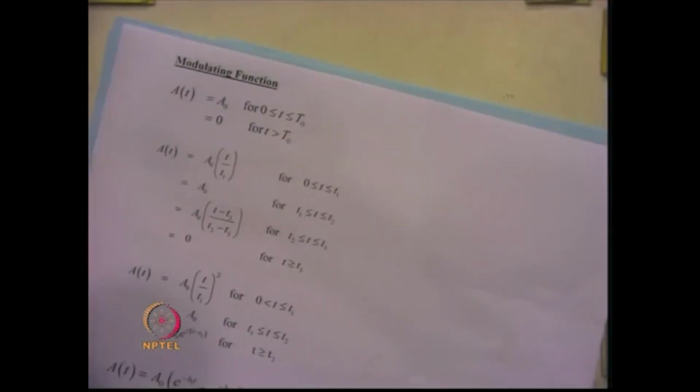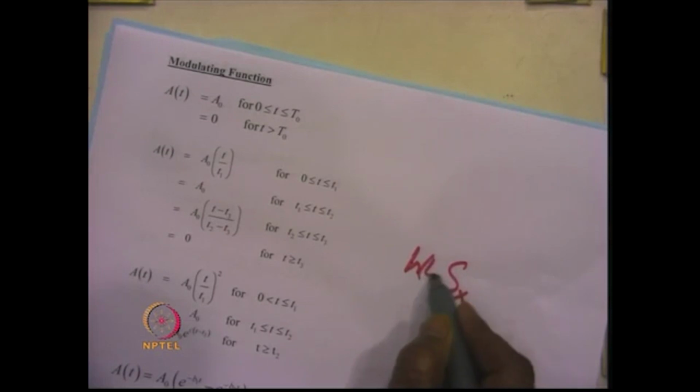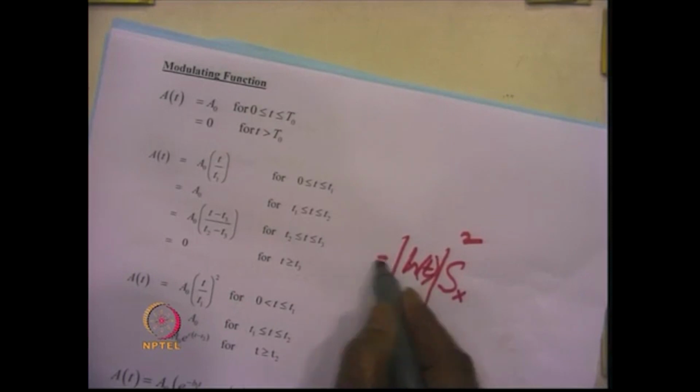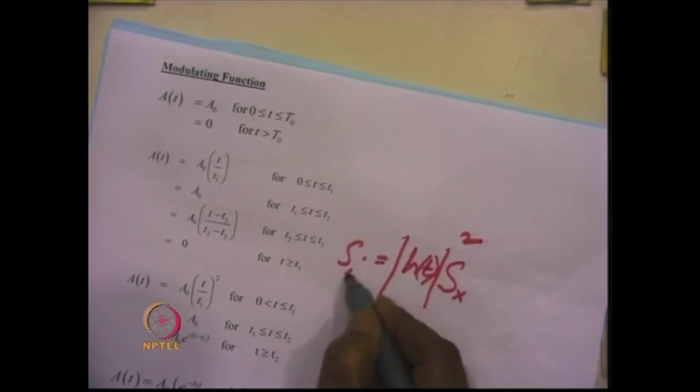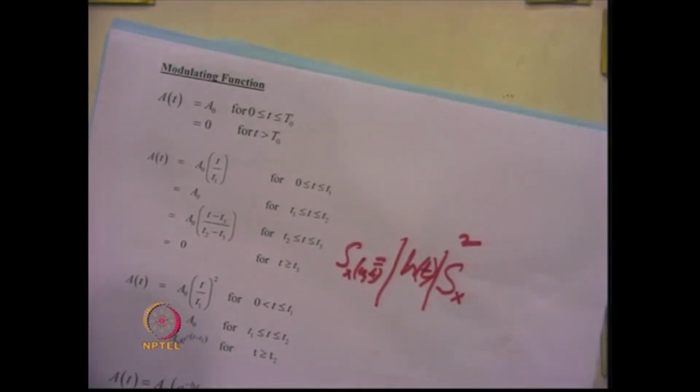And there we had seen that the power spectral density function Sxx of the earthquake is multiplied by a modulating function H(t) square, and this gives the value of the power spectral density function as a function of omega and t both. So, various forms of the modulating function were observed from the recorded data.